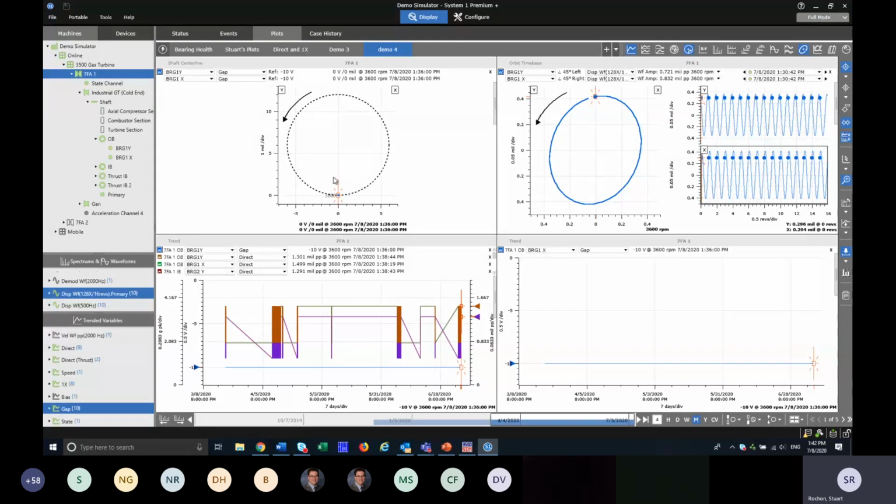And if you configure that clearance correctly and you set a reference point when the machine is stopped, lift oil is turned off, and it's a horizontal machine, the shaft should be sitting at the bottom center of the bearing, and you can very quickly see if you wipe the bearing. It can be very handy in making quick assessments, and also if you set this when the machine is new, you can see bearing erosion as that point sets lower when the machine is stopped and off lift oil.